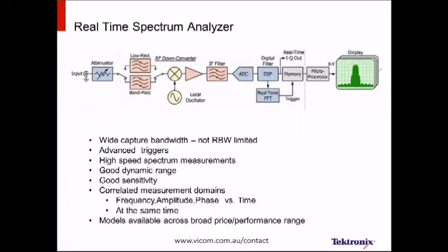Real-time signal analyzers are a little bit different than swept-tuned spectrum analyzers. We still have a preamplifier and a stepped attenuator and some filtering in the front end, but there's many differences when it gets into the intermediate stage. In this particular example, we have an ADC which is going to create time domain samples. We're going to digitally downconvert and create I and Q.